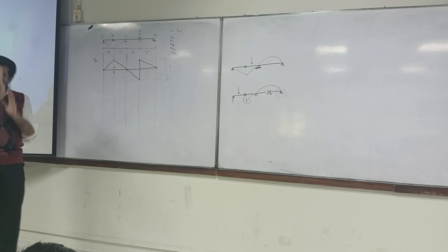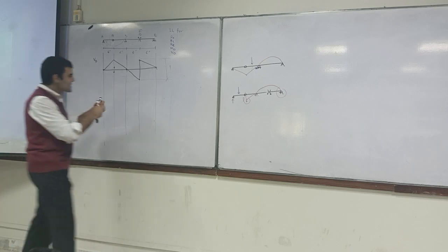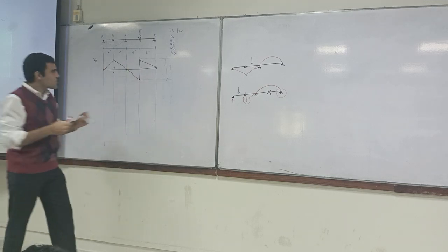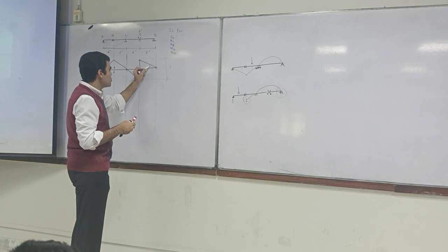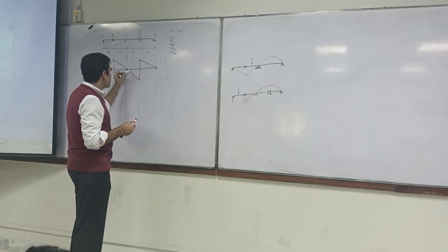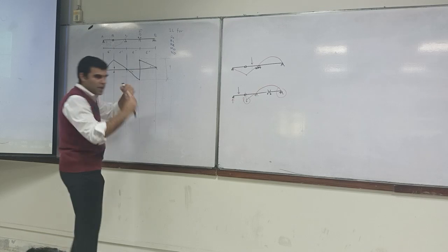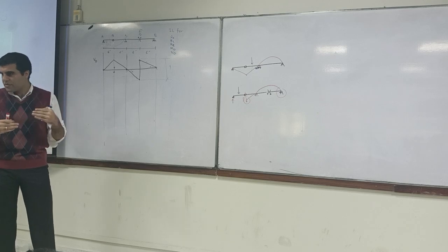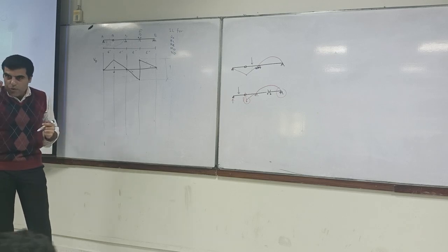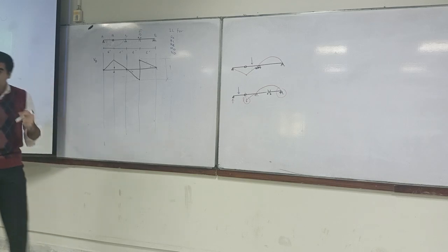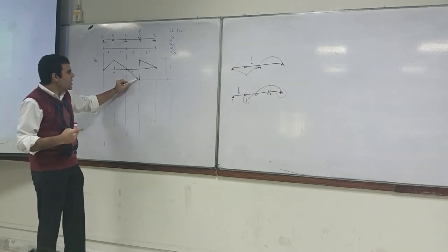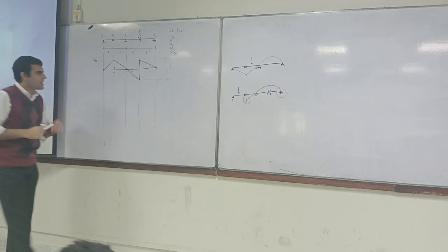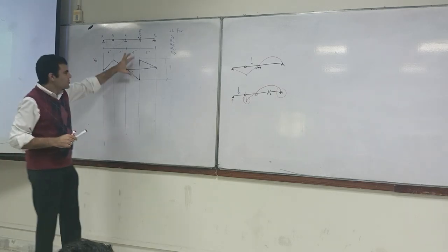Now in case of shear, I told you that because we are just releasing shear, the slope of this one must be equal to the slope of this one. Whatever I called it previously, if this is alpha, this one is also alpha, because these two slopes you're not changing. If you change the slope, that means you're releasing the moment also, which we are not. Release only one thing at a time. So we have released the shear and we haven't released the moment. Previously we had released the moment. Okay, so that is what we have now.